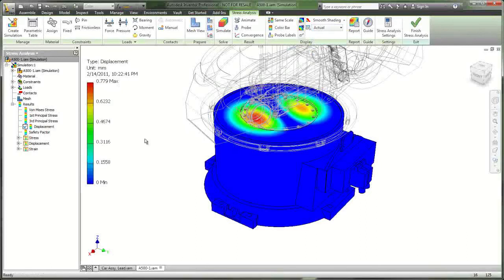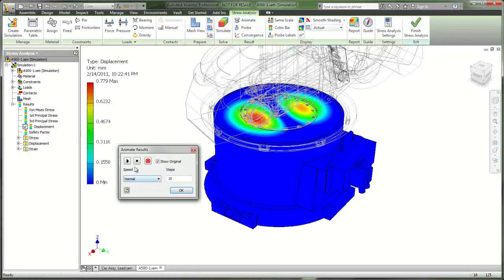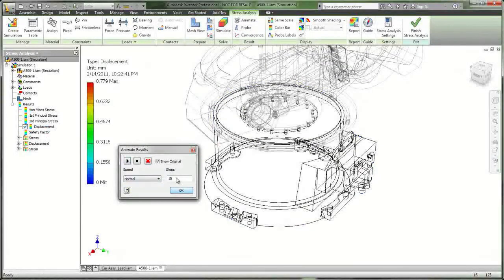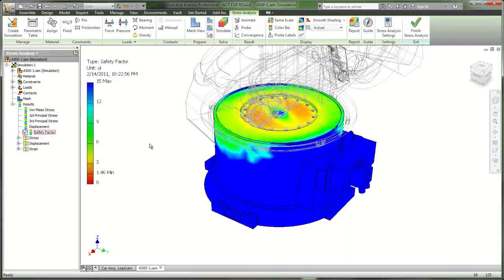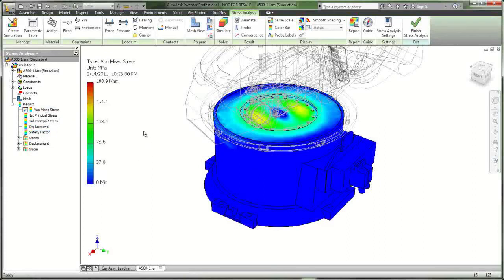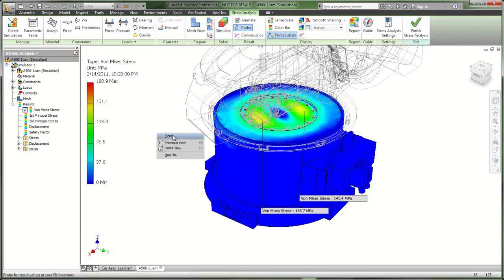You can see what our maximum loads are, our maximum displacement, and it is a little less than a millimeter, which for something as large as this piece, it is actually very, very good. The loads themselves are very low. This is well within the operating limit of the materials themselves. The safety factor is not as high as we would like it to be, but at 1.5 approximately, it is good enough. The probe tool allows you to essentially select areas of interest.